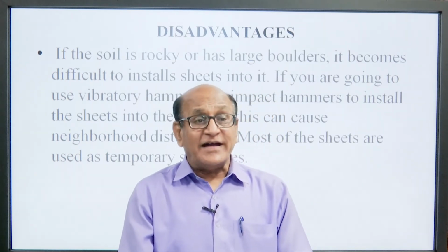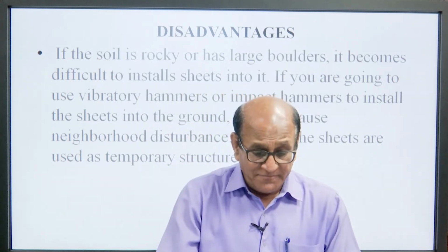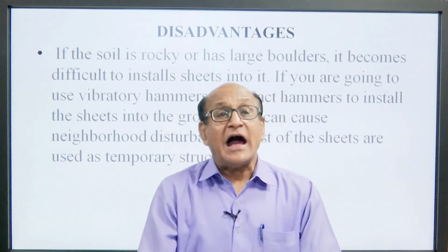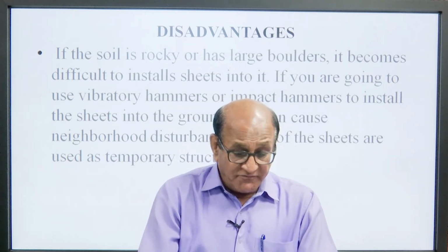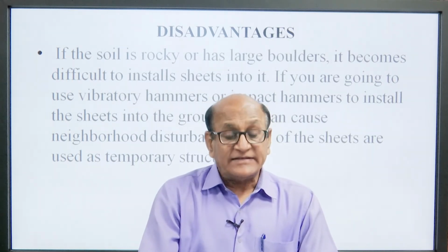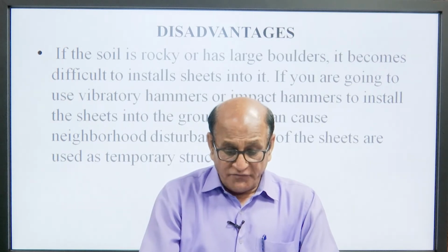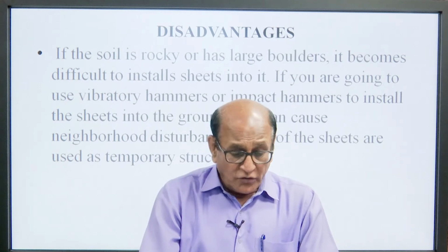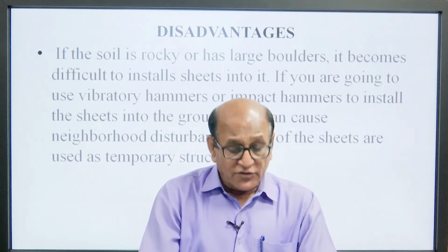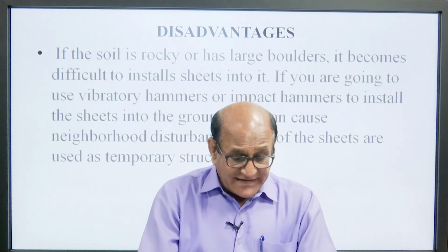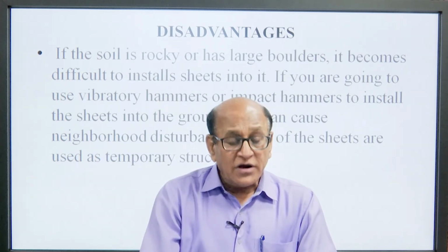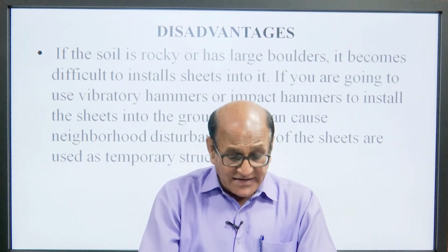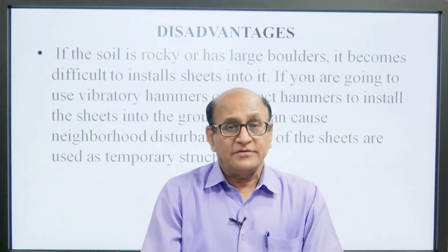Now, disadvantages of the sheet pile. If the soil is rocky or has a large boulder, it becomes difficult to install a sheet pile into it. If you are going to use a vibratory hammer or impact hammer to install the sheet into the ground, this can cause neighborhood disturbance. Most sheet piles are used as a temporary structure.